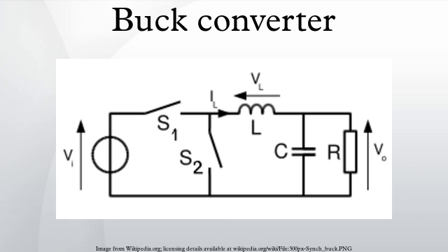Efficiency factors: conduction losses that depend on load, resistance when the transistor or MOSFET switch is conducting, diode forward voltage drop, inductor winding resistance, capacitor equivalent series resistance. Switching losses: voltage-ampere overlap loss, frequency-switched CV² loss, reverse recovery loss, losses due to driving the MOSFET gate and controller consumption. Transistor leakage current losses, and controller standby consumption.